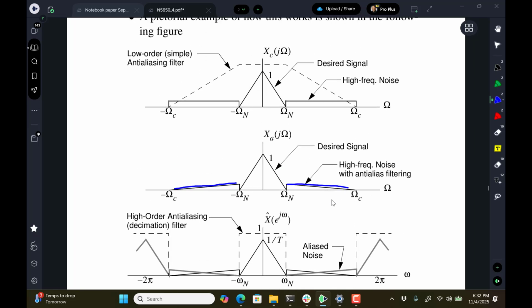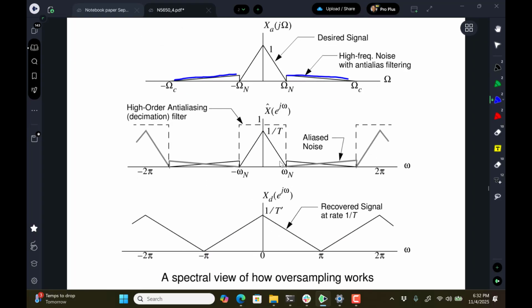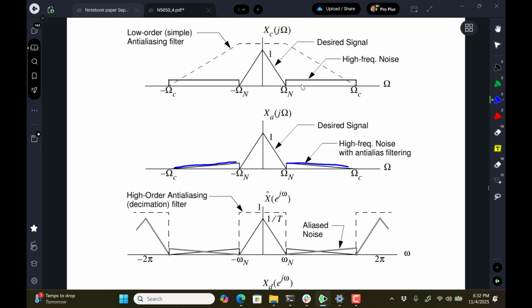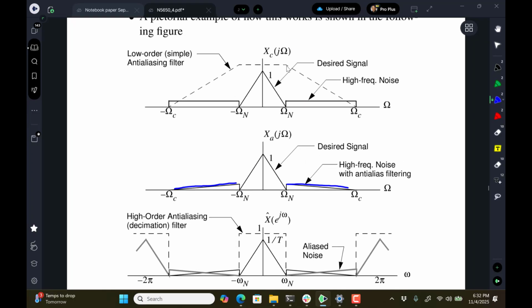And yes, there will be some aliasing above omega sub n, but we've designed our analog filter to be good enough rolled off by omega sub c. And of course, that's shown as 0 here, but actually it'll be so many dB down, maybe 50, 60 dB down.